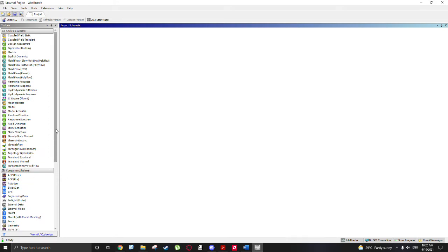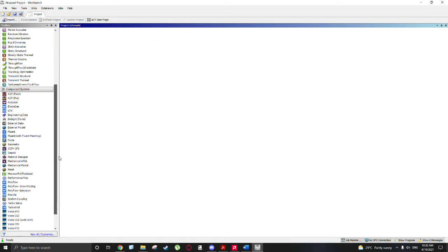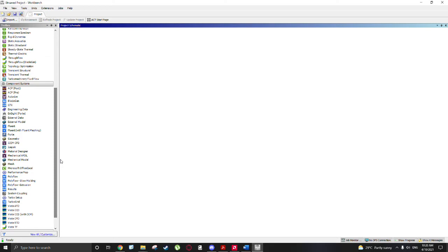It's important, if you're building your geometry in SolidWorks or another CAD program, to save that geometry as an IGES file. So first thing I'm going to do is import that IGES. This is just in the circumstance someone's built the geometry externally. If you've built it inside SpaceClaim, you won't need to import it, obviously.